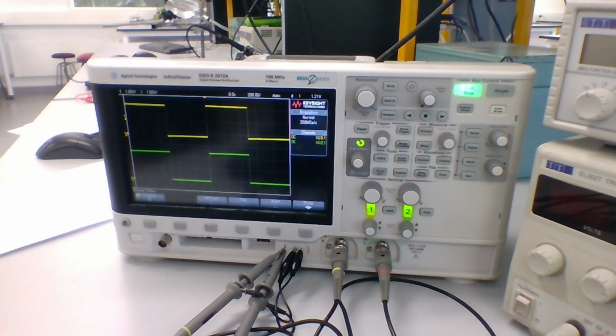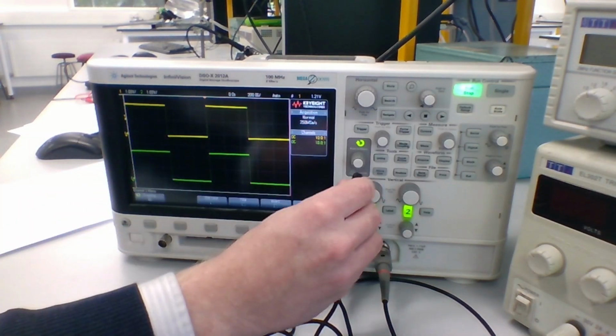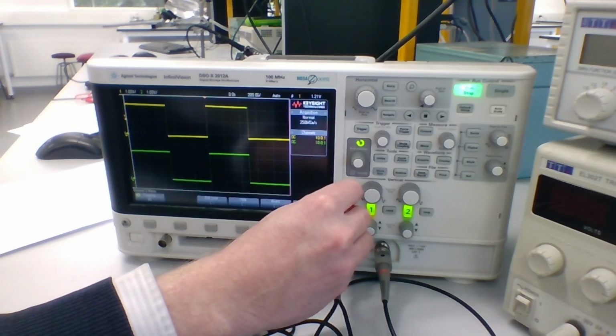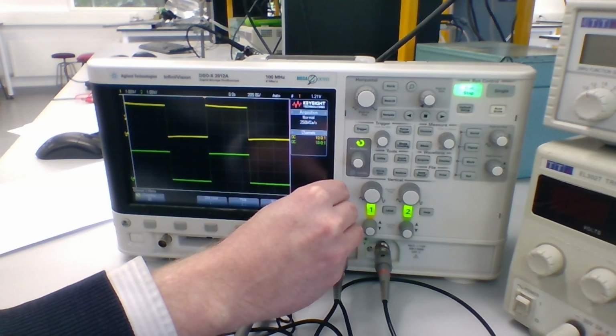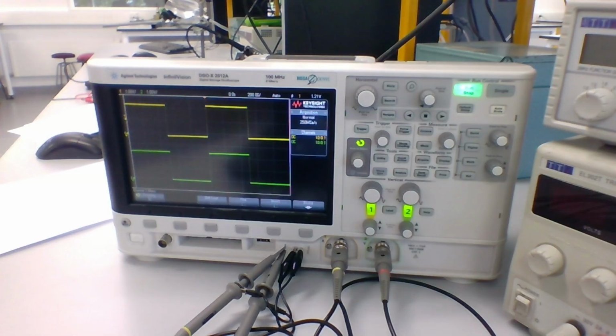We can see here, we can measure our voltage. We should, on this oscilloscope, at least have 2.5 volts peak to peak. Different oscilloscopes will have different voltages there and different frequencies as well. So you have to check the manual for those. But you should get a particular peak to peak voltage and frequency as well. So again, that lets you know that your test equipment is working before you go take a bunch of measurements with potentially faulty test equipment or things that need to be scaled.